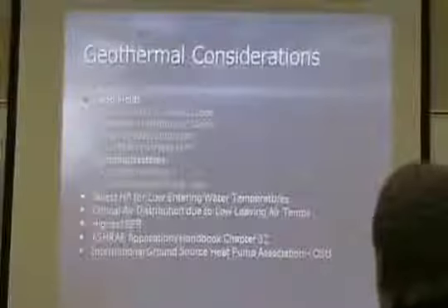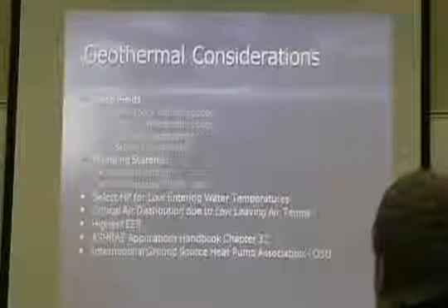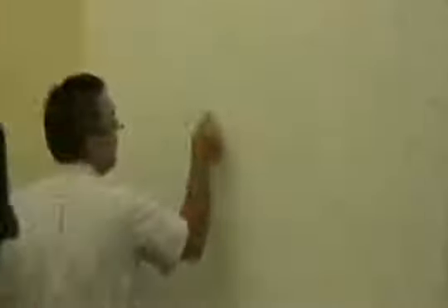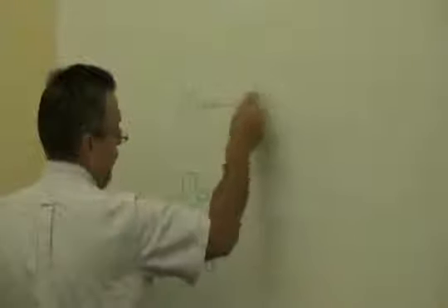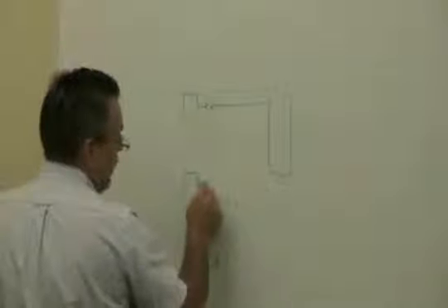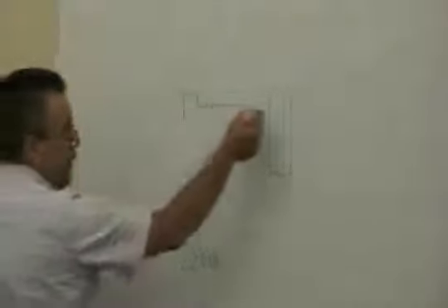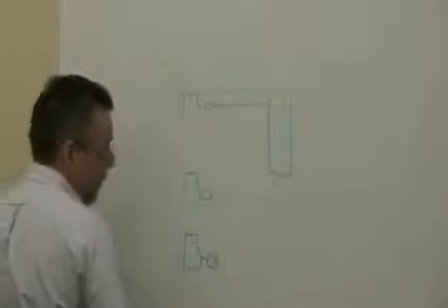Pumping systems, we talked about central pumping systems. You can also have that loop. A lot of people, especially in geothermal loops where you have a series of heat pumps, will put little individual pumps on each heat pump. They might actually go to a well right back into the building. Generally, that's about the only time you put individual pumps on the units, when you've got an individual drop in a geothermal application.